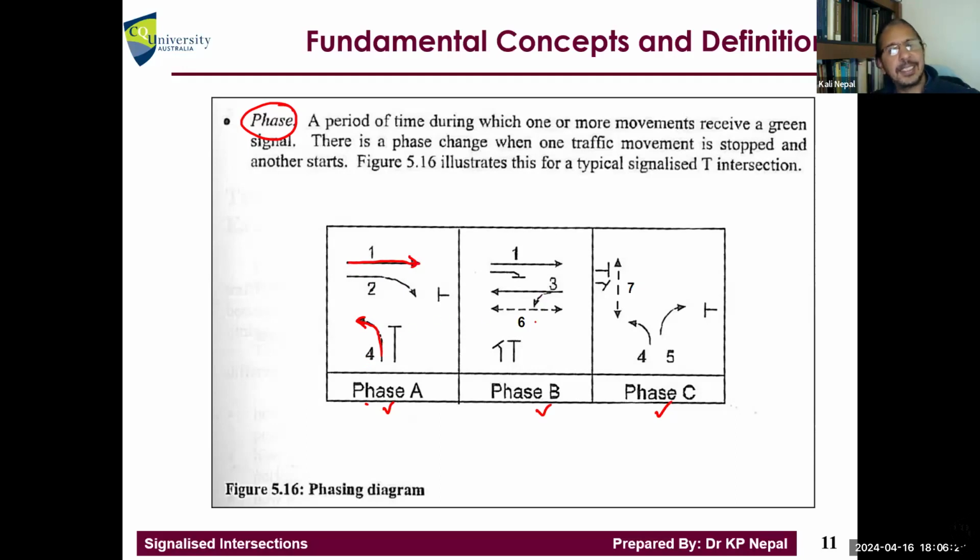And next, you see, we stop the south traffic as well as the right turning traffic. We keep going from 1 and we can allow 3 here. The reason is 6 is a pedestrian movement here, right? They give way to pedestrians and go that side. So we need movement number 1 there, so we can have this third phase. And then we allow the south traffic to go both ways.